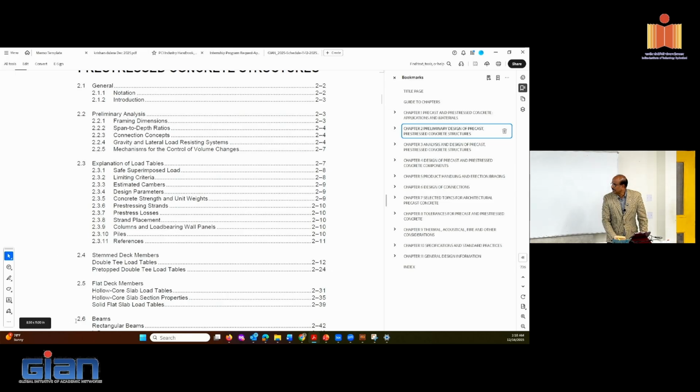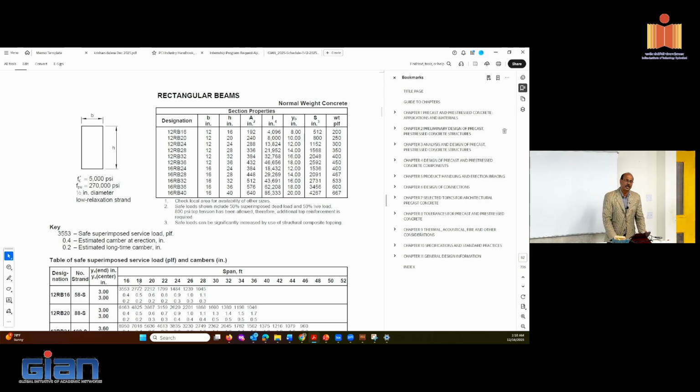And you will also realize that by picking the standardized product, the cost will also be pretty competitive. So if you go and ask them, oh, can I make it a little longer or maybe a little wider, then they have to make specialized formwork and the cost is going to be increasing as well. So here's a simple rectangular beam.